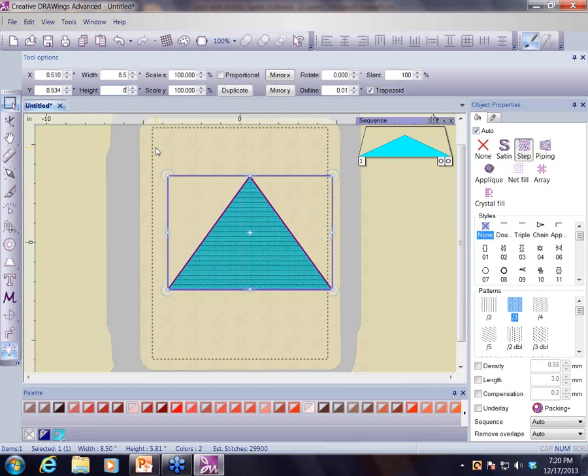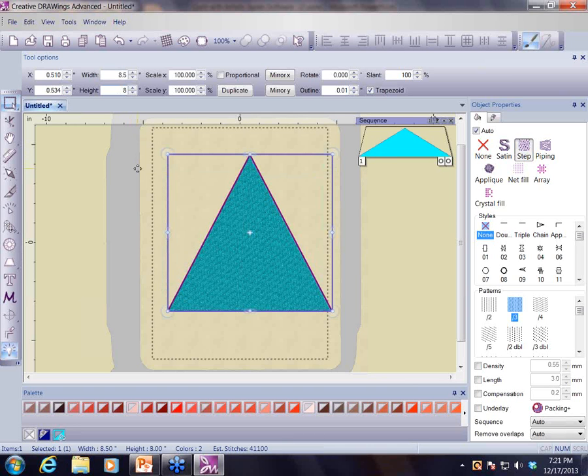You can also go into your software and change that from inches to millimeters or millimeters to inches. So whatever works easiest for you. Okay, so I've changed those figures here. Now to make sure that they both take effect on it, I want to touch the enter button on my keyboard, and that finishes that process for me.